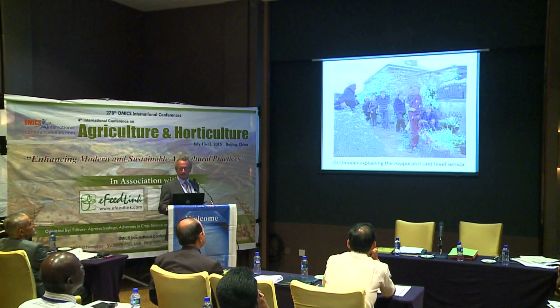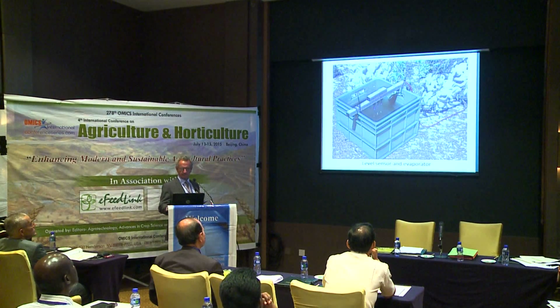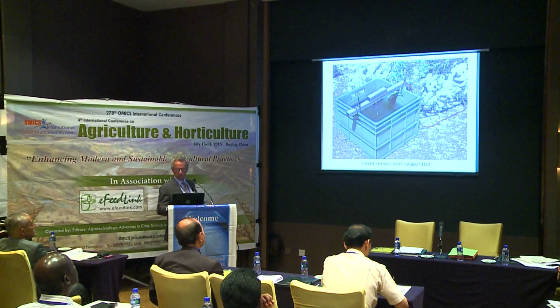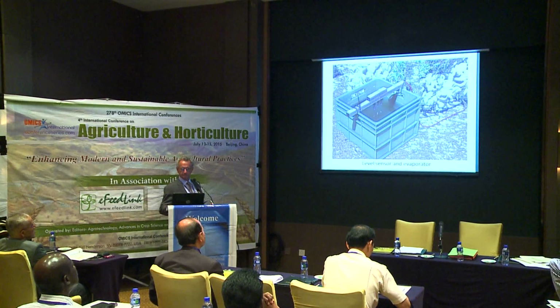Here I'm explaining the evaporator and level sensor. That's the evaporator and level sensor. You can see the white powder on there. That's because we're using bore water in this case, and it's got a very high salt content. So as soon as the water evaporates, it leaves a deposit of calcium.